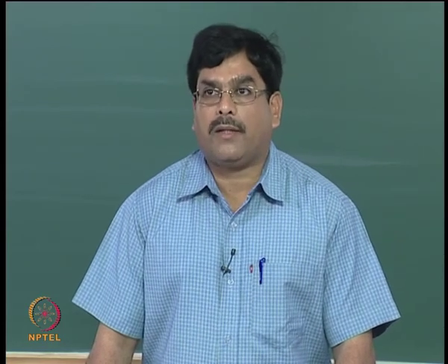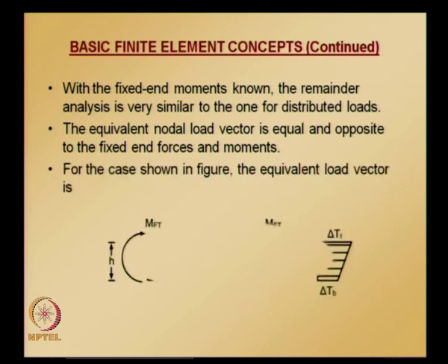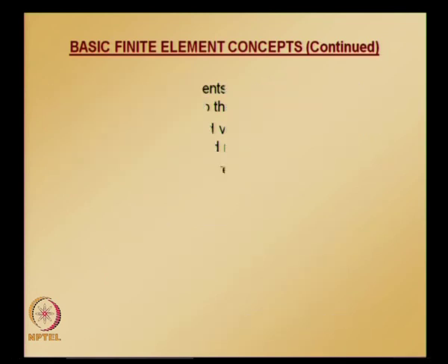So the equivalent nodal vector will be given by this one, using the sign convention that we adopted for nodal forces and moments. Nodal forces are 0 and nodal moments are coming from the fixed end moment because of restraining the deformation of this beam element.